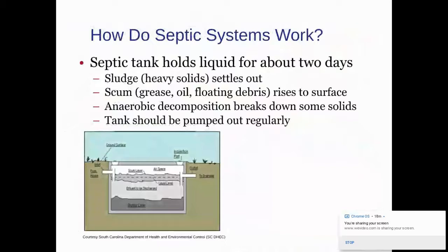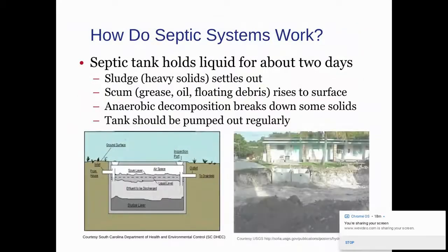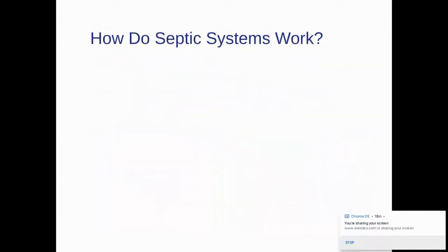Sludge, heavy solid, settles out. The scum, grease, oil, and floating debris rise to the surface. You have anaerobic decomposition that breaks down some of the solids. But again, especially the scum, the grease, the oil, all that stuff, that's not good stuff. You want to pump that out on a regular basis. This is an example of a septic system being installed.